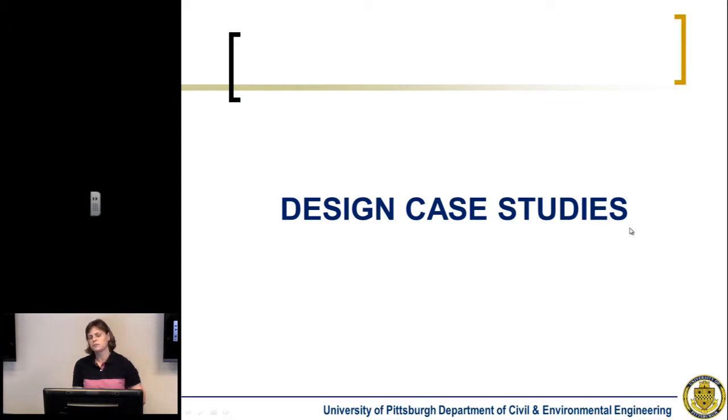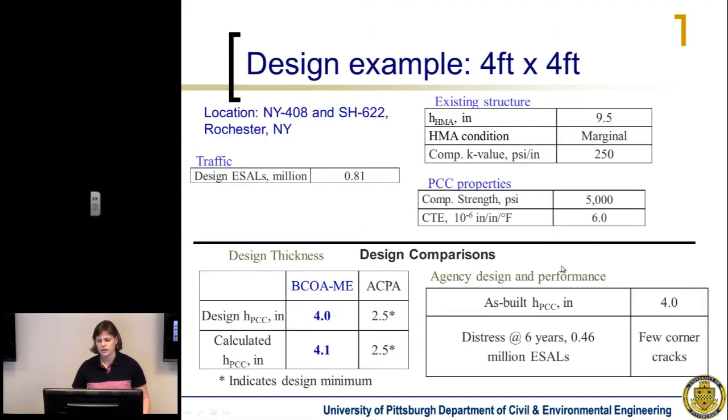So we're going to say for these pavements that have been constructed, and most of them were designed and constructed at a time when we didn't really have a procedure available, so it was just a best guess, if you will. So we'll compare these procedures with their performance and the predicted overlay thickness that would have been provided by the BCOA, as well as with the older ACPA and Colorado DOT procedures. I should mention here too that the BCOA app put out by ACPA is quite similar to the ACPA procedure. It was just the ACPA procedure incorporated into that app.